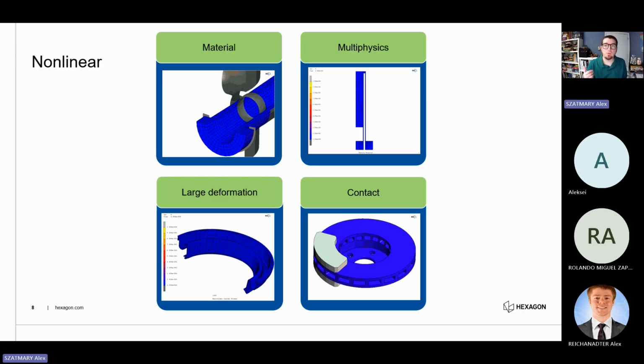And finally, if you are wanting to make sure that the structure is safe, especially to demonstrate that a composite structure is equivalent to one that's made out of welded tubes, a space frame structure, then finite element analysis can be very helpful for design of things like composite sandwich panels, so that when you go to make your 3-point bend test specimen, you can get it to pass the first time.